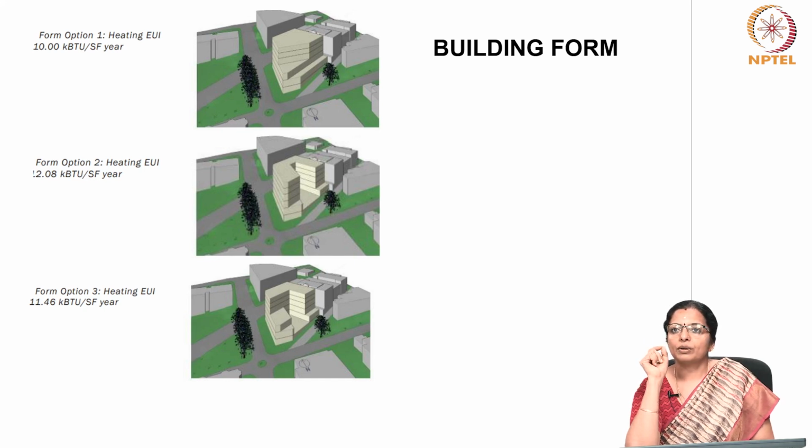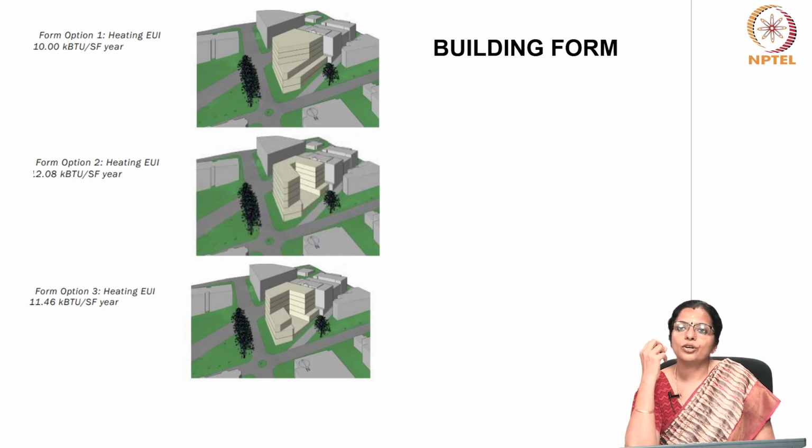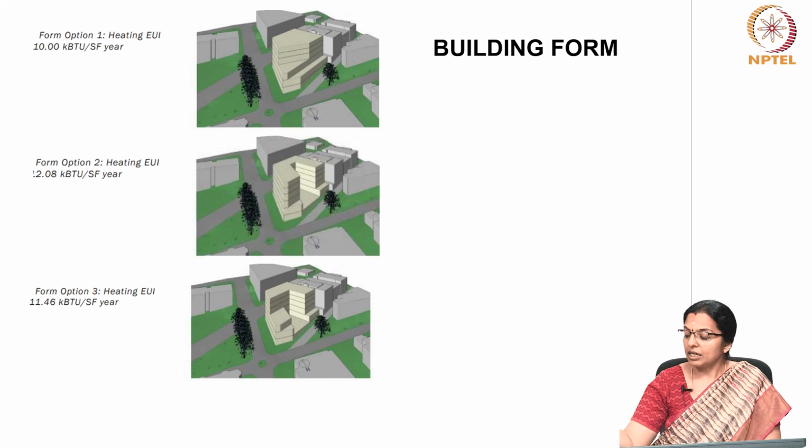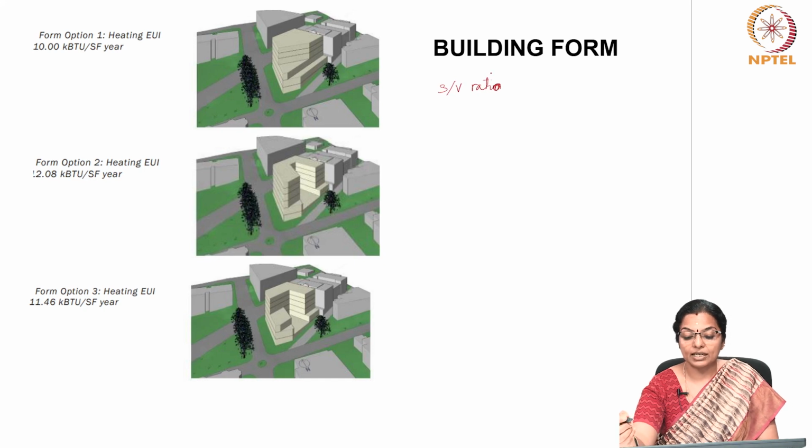Each dimension of the building's design, its energy and water use, its durability, its longevity, the toxicity and origins of the materials, its function, form, and organization all had exceptionally high performance thresholds to meet. A variety of building forms were tested, each with different surface to volume ratio. As we had seen in the previous class, how surface to volume ratio matters and aspect ratio also matters.